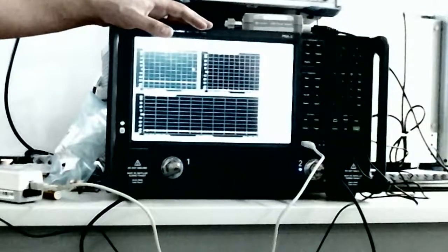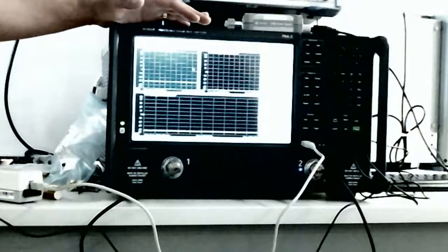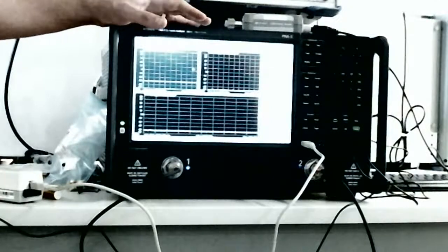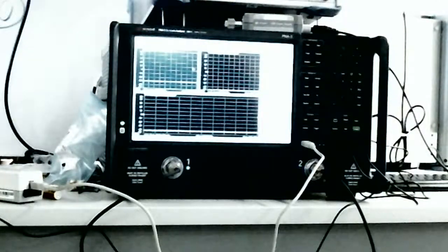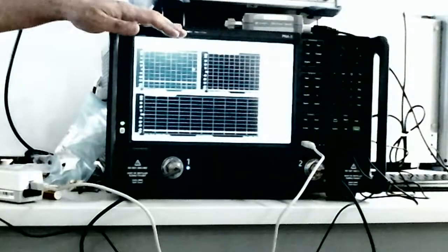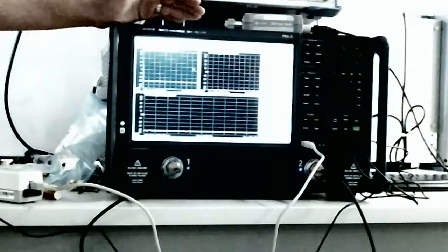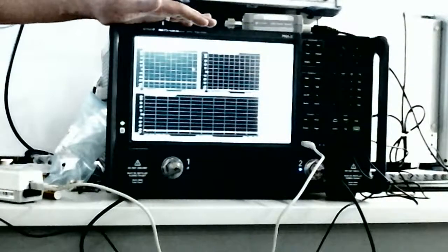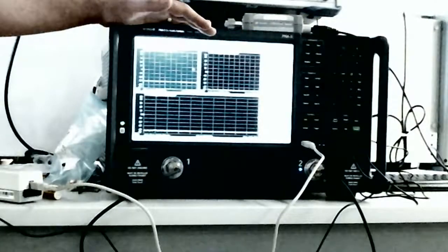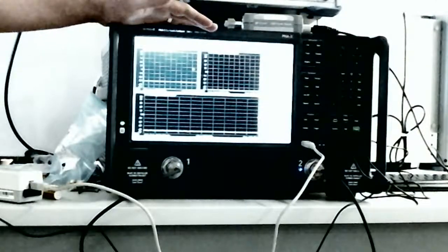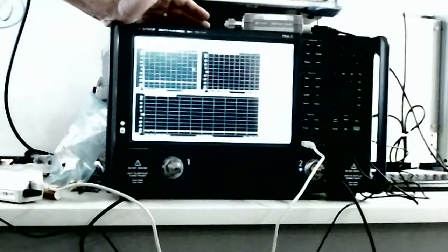In some cases, over frequency, on a really good day, if you take a look at what happens when you have sort of the optimal settings, and all of this is in the data sheet for the PNA, based on the eCal you're using, you can get down to, I think, 52 in some frequency bands. So anything above 40, we're really kind of at the noise limit of the directivity. So yeah, I mean, we're there.